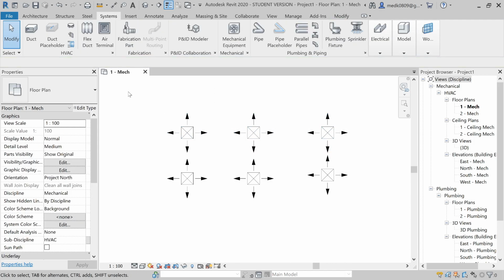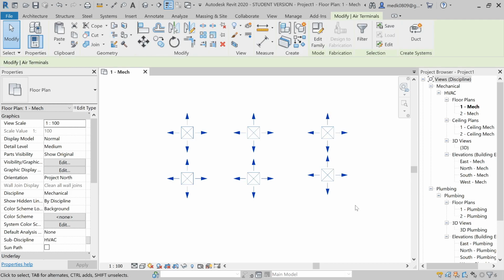Now let's see the window from left to right. So we'll press the mouse on the screen and draw this window. You can see if I'm trying to touch the element with the window, it is not selecting it. But if I cover the element in the window, it is selected. You can see if I select all the elements within this window, they will be selected. If any of the elements is not covered completely, it will not be selected, like these two. So this is the difference.